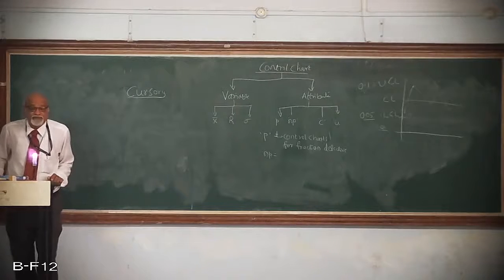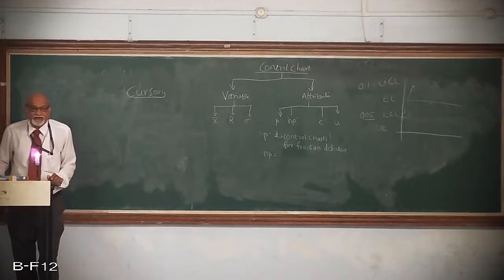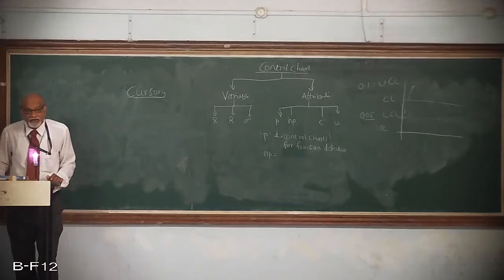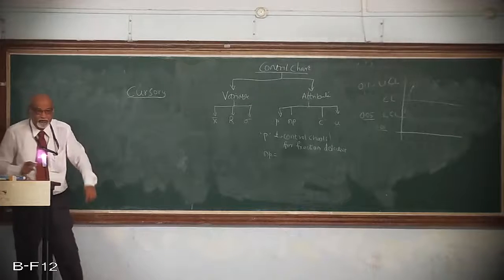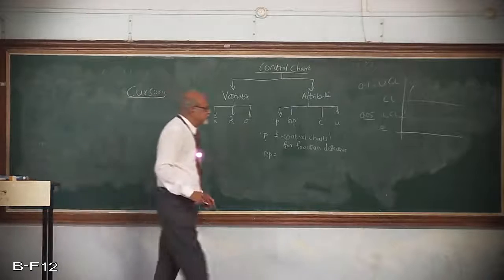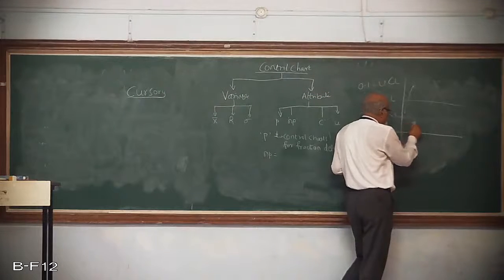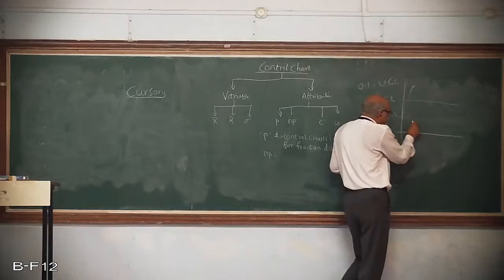or 1 defective. What does it mean? What should I do? So that question you might be getting in your mind. I can perfectly understand. If it is between 5 to 10 defectives, okay, I can understand. If it is more than 10, I can understand. If it is less than 5, why the process is to be stopped? Is it not? You are getting some clue about that one? Because I am getting frequently when I take, it contains 2 defective or 3 or 1. That means it is lower than the lower control limit. That means the point has fallen outside.